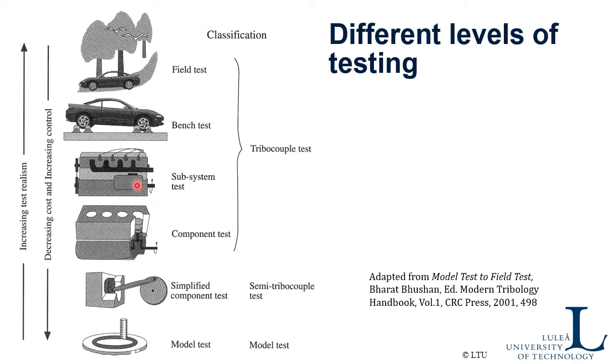Or even better, you run it in an engine test. You operate the engine fully, then you have the exhaust gases, you have all the vibrations, you have the temperatures, exactly as it is in the real engine, in the real case. Even better is if you can put the engine into the car and run the car in a bench test. Then you also see the interaction of the engine with the rest of the car, or eventually then, as I said, the field test. So the cost is increasing if you go this way, but the realism is also increasing in this direction.